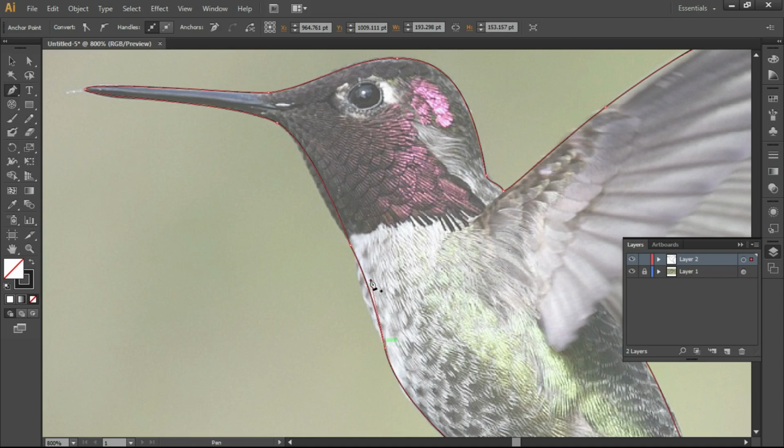See why we are pressing this P and Alt, click, drag? Because otherwise what will happen if we simply try to move this shape is also getting distorted. This side was perfectly done. This side was perfectly done. We want to edit only this one, so I'll press Ctrl Z. I want to move only this handle. I don't want to distort the shape over here.